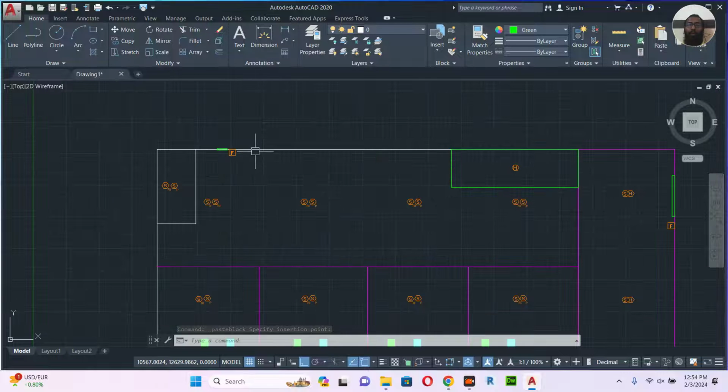So there is some standard. If you see one building drawing, there is a drawing called life and safety. In the life and safety drawing, you have to submit to the government to take approval. In that one, in case of fire, emergency exit, how many meters there will be to exit. So let's say one guy is standing in a particular place, he needs to run to the exit how many meters, and what is the route, everything.